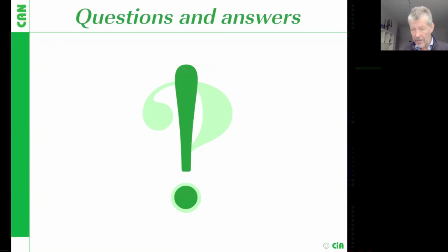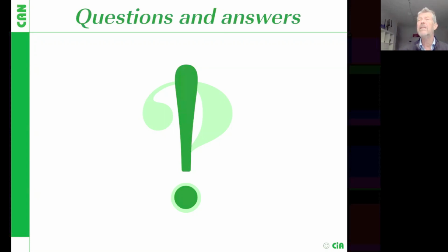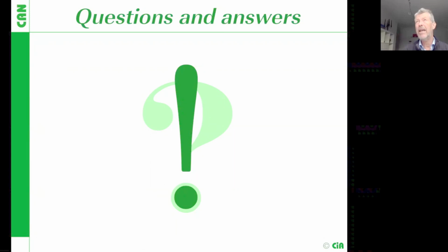If there is no BRS bit, when exactly does the bit rate change? Is it similar to CAN-FD, where the switch happens mid-bit? No, it's not mid-bit anymore. So this is different. The details are not yet specified, but it's clear that we don't need the BRS bit. We now have the 3 bits. You have seen the ADS and the DAS. This means the arbitration to data phase switch. This is 3 bits where we change, and so we don't change in the middle of the bit.